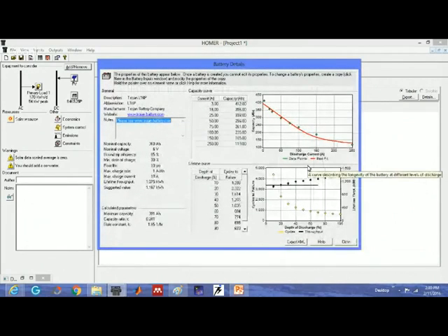This is the chart of that battery. This is the data sheet of that particular battery. Even some website is also given to you. See, this is a Trojan L16P battery, right? You can find out how many ampere hours, how much voltage, round trip efficiency is 85%, right? But the problem is that you cannot change anything. This is an inbuilt system, right?